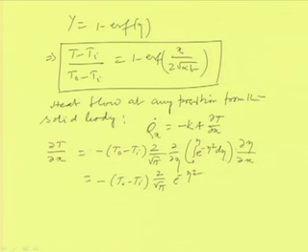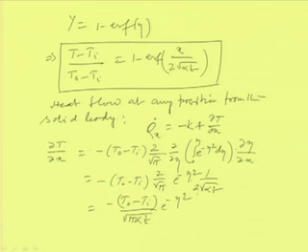So, the derivative and integral cancel each other. So it becomes minus eta square into, and the del eta by del x term, we have seen already, is 2 root over alpha t. So this gives: equal to minus (T naught minus T I) by root over pi alpha t into e to the power minus eta square.